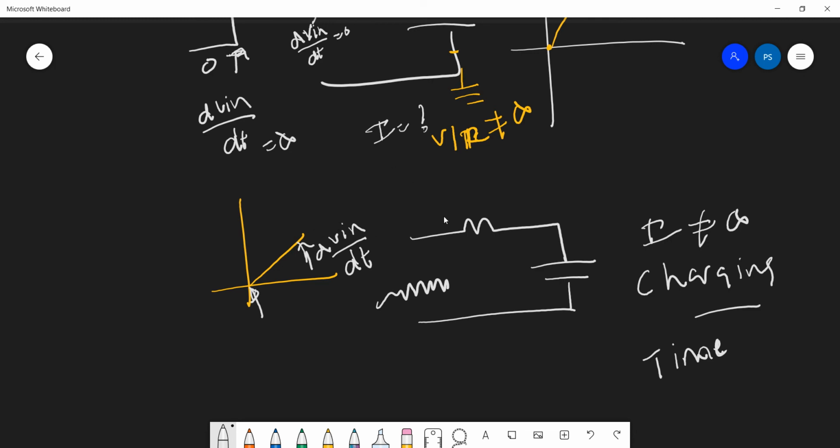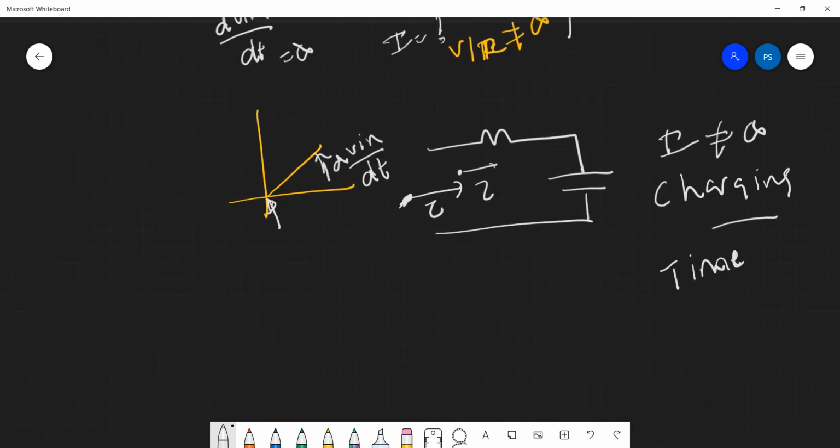So you are applying a constant change at every time. For example, let's say I feed some signal here and it will respond after a certain delay. Let's say that delay is some tau. Then you apply another signal here, it will respond plus some tau. What it means is, you are doing a change in the signal at every time and the circuit requires its own time to respond to that. And that time is fixed, right? Because the time constant of this is R into C.